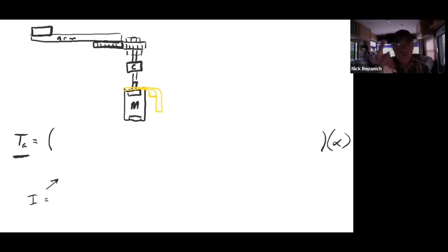So rule number one with this is start with the inertia that's the furthest away from the motor. And we're going to work backwards and we're going to list them, because every single term gets simpler and simpler as we get back towards the motor. So in this case, the inertia is that one. We need some labels, right? So we will label this, we'll call this mass. That's the mass. As odd as this sounds, I'm going to write this inertia of mass.